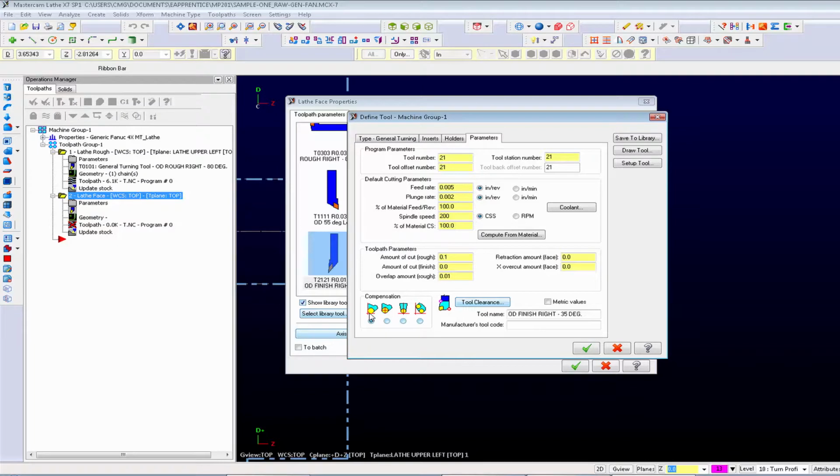So with intersection point compensation, you can adjust the diameter compensation versus the compensation in Z, but you couldn't offset the radius on a 45-degree line very well, or as it transitions along a complex contour.